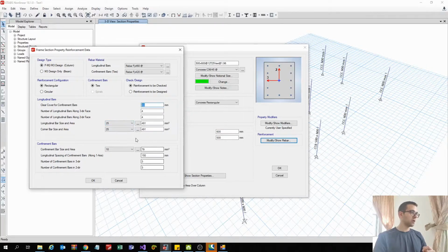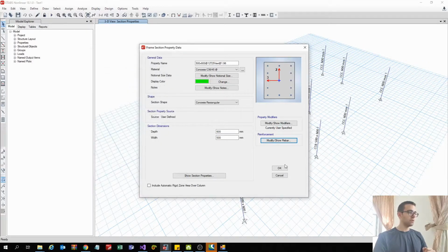I haven't done much work on confinement bars. That might be addressed in the future. And 460 and 420, that's perfectly done. Now it's important: these here can still have visualization issues. They will not show the correct number of bars, but when you export and re-import the model, they will. And if you decide to proceed without it, you will still get accurate results and you'll not be impacted. If it bothers you visually, export, import, and we'll do that at the end as well to demonstrate it.